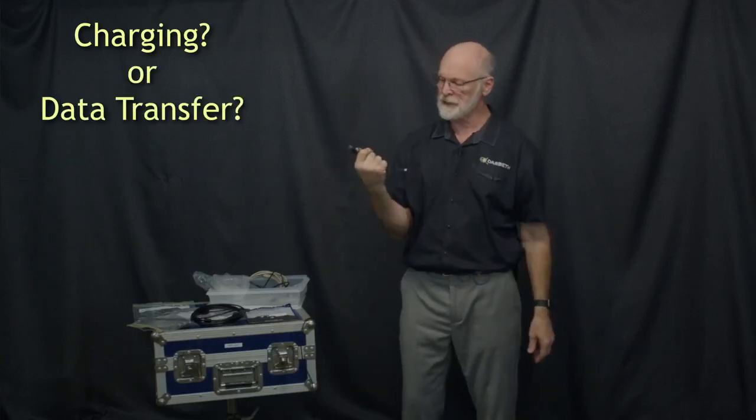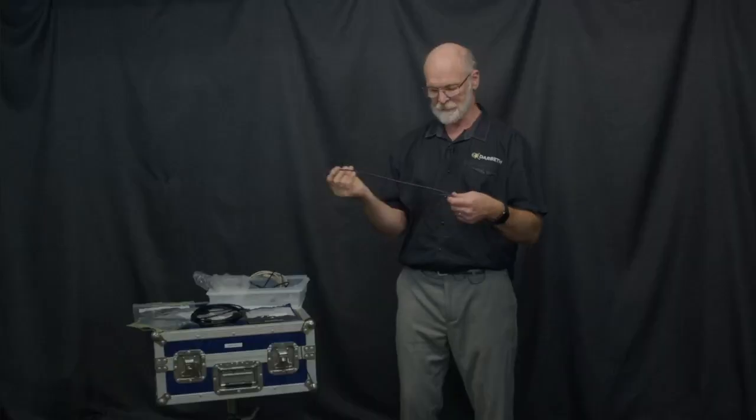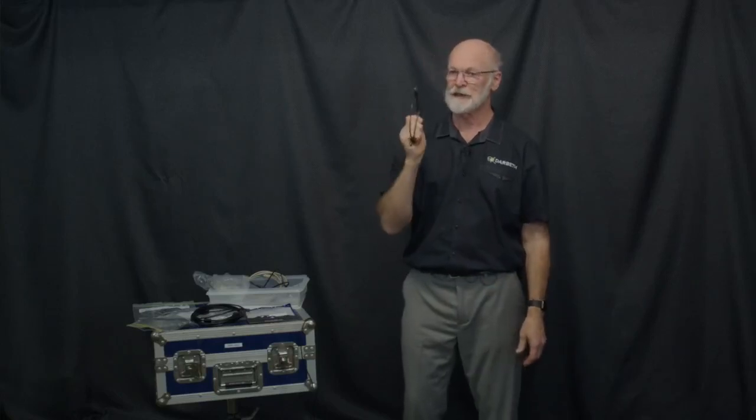And generally speaking, you cannot get a cable which will give you high data transfer and the higher power for charging. So if you find a good cable which works for your charging, identify it. If you find a good cable that works and gives you high speed on your data, mark that out as well and know where to use it and when to use it.